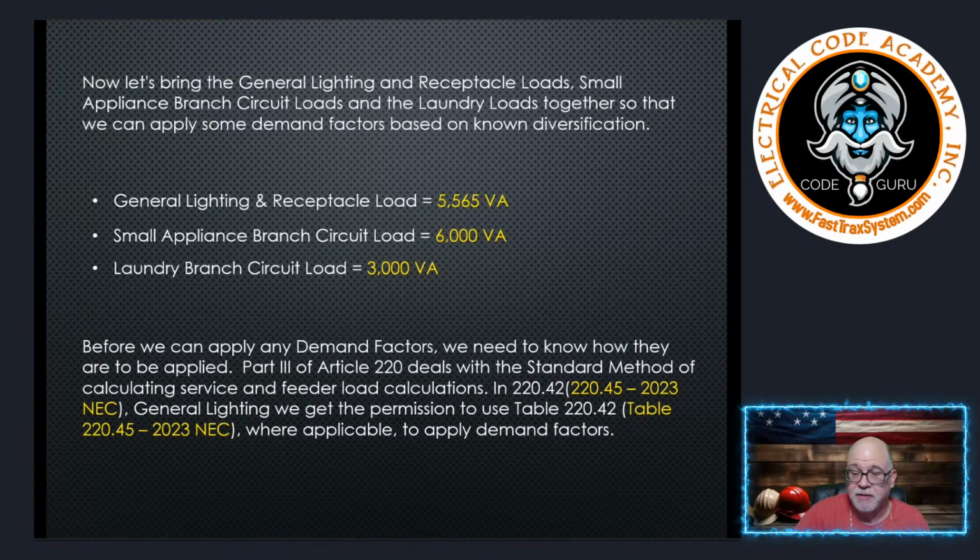Then you don't have to install the receptacle at all, but you're required to have the laundry circuit. And in a single family dwelling, you're required to install the laundry receptacle outlet. And I believe that is in 220.52(D), if I'm not mistaken.